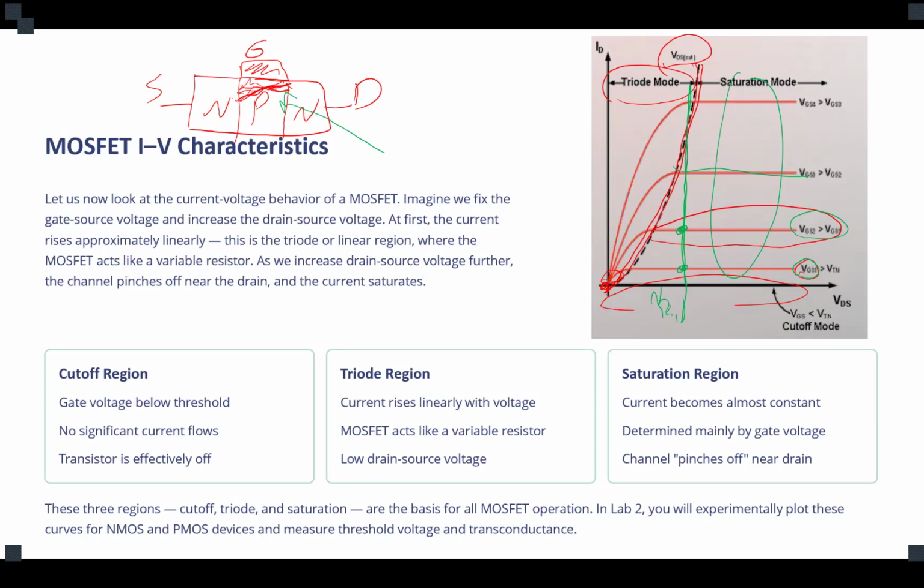If we have high temperature, the characteristics of a semiconductor change. So you start with certain characteristics, and over time you would end up with different characteristics for your MOSFET. So in triode mode, even if you set that perfectly at the beginning, later on you are going to have a deviation.